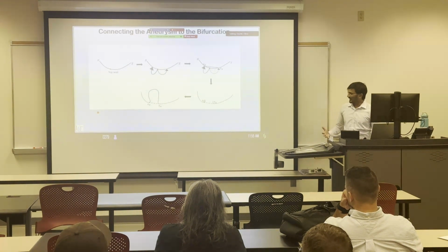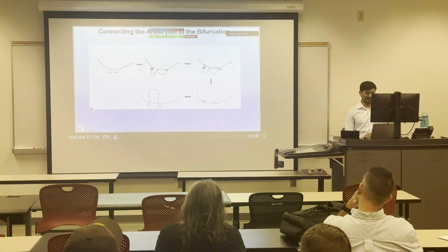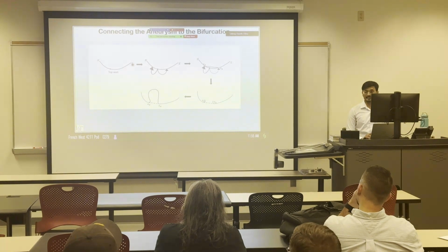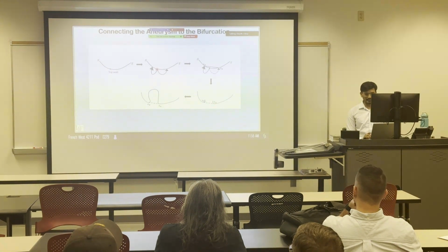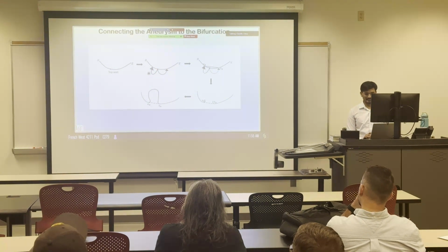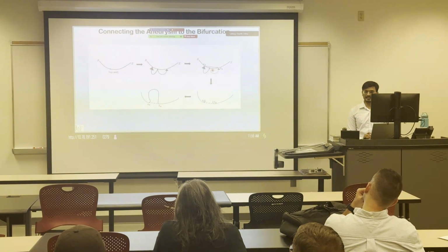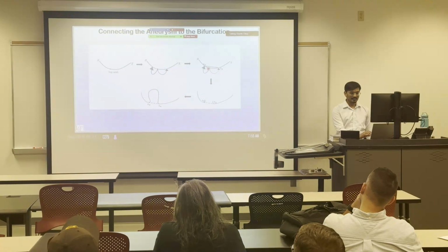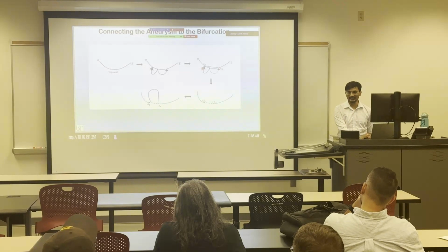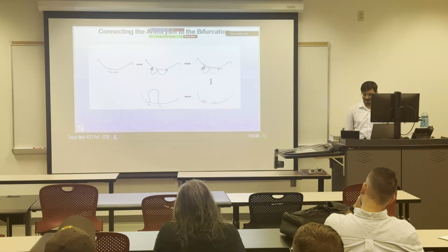And so the next final task is to connect the aneurysm into the bifurcation. Here what we do is, we parameterize the top wall. This is the top wall, and with respect to that parameterization, define a point where you want to start, and from that starting point you go forward and backward, so that the distance between these two will be the aneurysm neck length. Aneurysm neck length is a straight line, not taken along the curve. Now we have the start point and end point. Then you can construct the aneurysm on this top wall according to the way I described earlier.